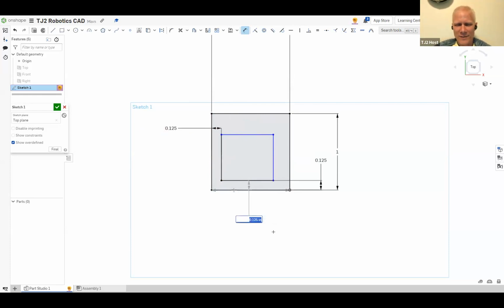You've already dimensioned that one. It's not going to be happy if you do this one. Go ahead. See how it made it gray? The gray one is saying it's over constrained, so it's like, I'm just going to make this one a reference dimension. You can leave it or delete it. It doesn't matter. You would need to do these two here.